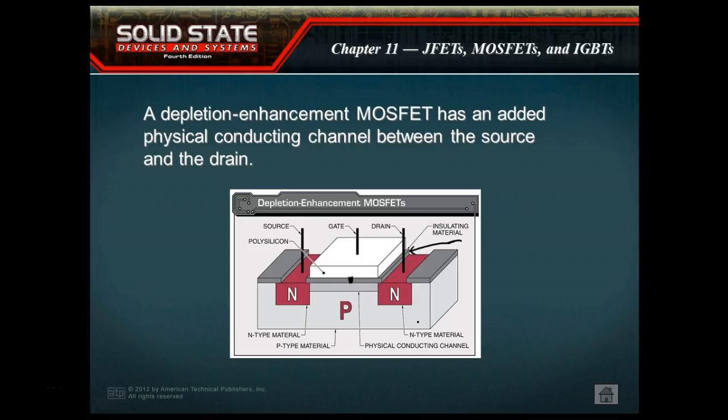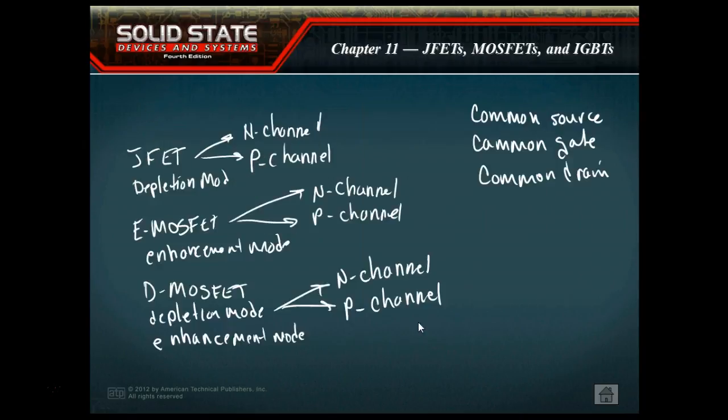But when you get into these MOSFETs, and a lot of people just call this MOS, by the way, so if you ever hear the term MOS, they're talking about MOSFETs. And of course, all the memory in your computer is MOS, so you need to be really careful if you work inside a desktop computer to make sure you guard against static discharge. And we'll show you that on Tuesday if you're reminded.